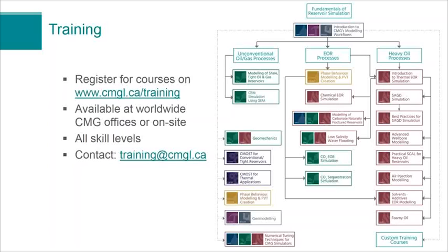So we input a range of pore volumes in CMOST, and then it was handled by a trigger in STARS. So we made the trigger a CMOST variable, and so the trigger at which the polymer injection stopped would determine basically the pore volume injected.